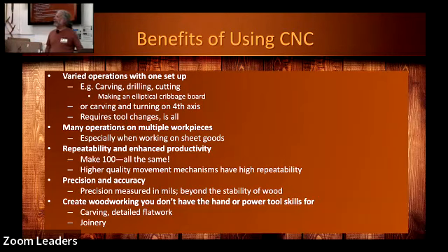Questions about this slide? Is this resonating with anybody? Yes, sir. How sharp is that inside corner? The question is, how sharp of an inside corner can a CNC machine make? Part of that's dependent on the bit that you use. The sharpest corner that you will get is a function of the radius of the cutting bit that you use.